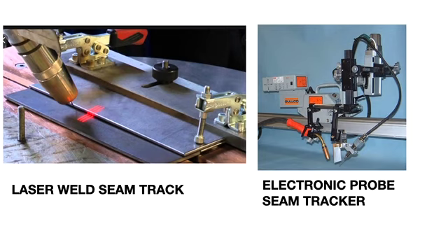Before the welding is performed, the machine will move through the joint with the laser and reconfirm whether the position of the welding torch is correct, and some minor adjustments are done automatically, not with the aid of an operator. And then only welding is performed.